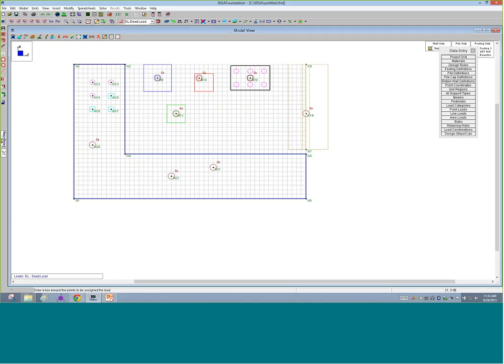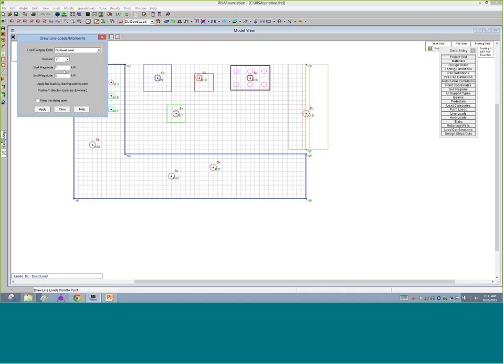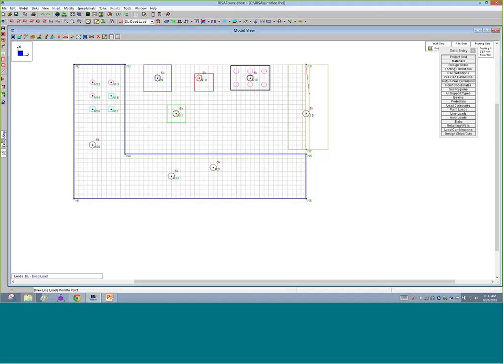You can also go ahead and do line loads. If we click on line loads, you can see they can be the same types of categories. We can tell the program here that it's going to be maybe 5 kips per running foot. Maybe that's a little large. Let's just say 1 kip per running foot. Again, that's a positive direction. It notes it here just in case you forgot. Positive means downward. And I can say apply, and I can draw that on top of my retaining wall.